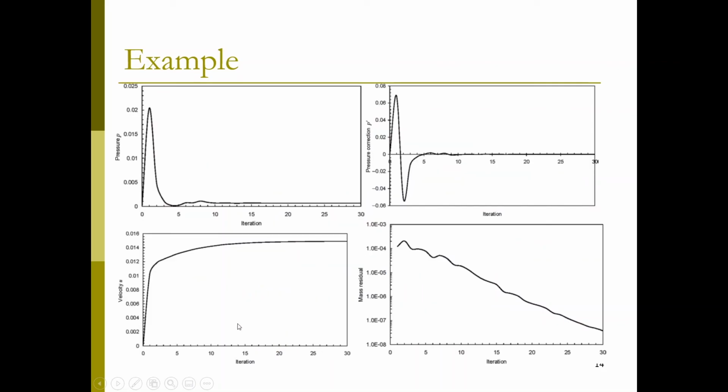You can also see the effect of the iterations on that field. This is the convergence criterion which is being used for all of this. Once we achieve this, we make sure that the mass residuals are very close to zero, and the velocity and pressure fields will automatically follow as well. They will be converged. As we can see, the change of the values of P and U here is almost asymptotic. It remains almost constant when you do more iterations. So it is getting closer and closer to the correct value.